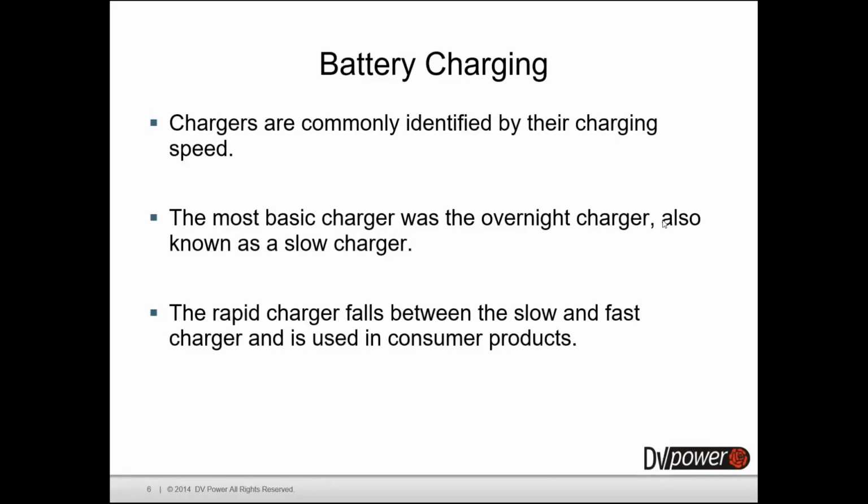But you need to know that the working conditions are one thing, discharging conditions are a second thing, and the charging conditions are a completely different thing. So if you see in a manufacturer data sheet that the battery can work at 0 degrees Celsius, that only means that the battery can work at 0 degrees Celsius, not that you can charge the battery at 0 degrees Celsius. That especially applies to lithium-based batteries.